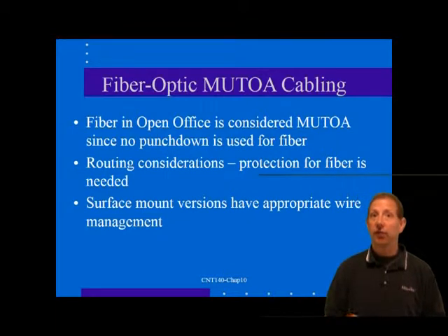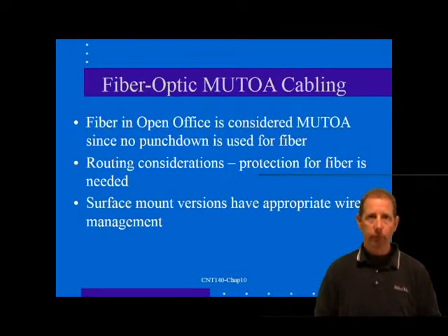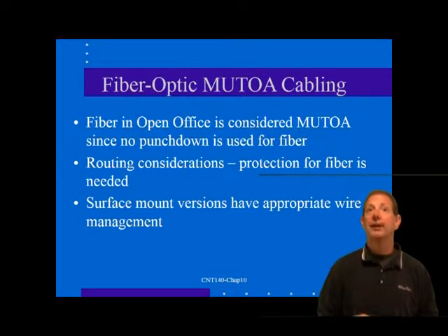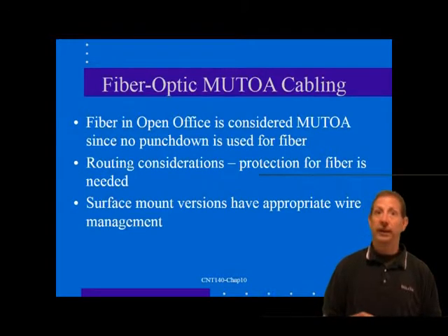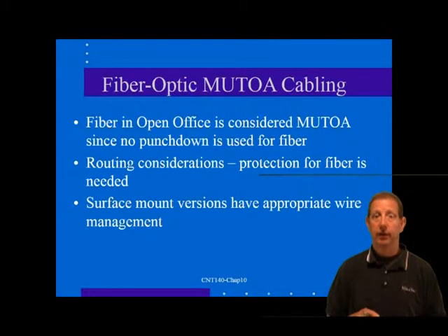The insertion and return loss that result from each termination are comparable to a normal termination, and the only parameters that must be watched are the total path loss and the optical bandwidth. As a result, the point of interconnection for the fiber runs can be just as easily placed in the open office area as in the telecommunications closet.